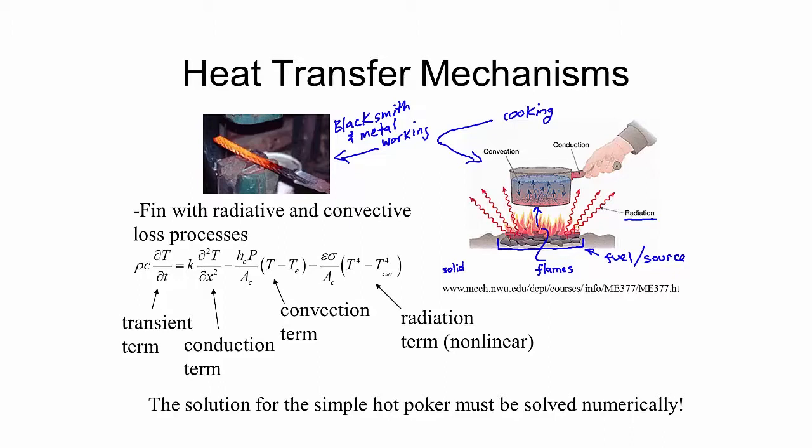These solid carbon particles, not unlike the smoke that you see in a candle flame, when they're heated to very high temperatures, they look a lot like what this piece of metal looks like. They start to glow orange or glow red. And so what we're seeing really is these soot particles, and they are doing something called broadband radiation. So these things are radiating in this high temperature flame environment. And so that's one thing that, from a heat transfer perspective, affects the system.